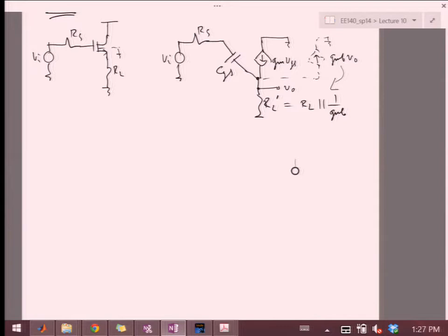So the reason why I'm not going to do the zero-value time constant or open circuit time constant immediately is because I do have this CGS directly on my path, and it's a rather large capacitance. So I'm guessing there will be a zero there that's actually pretty important, or at least that, yes? So I neglected it.